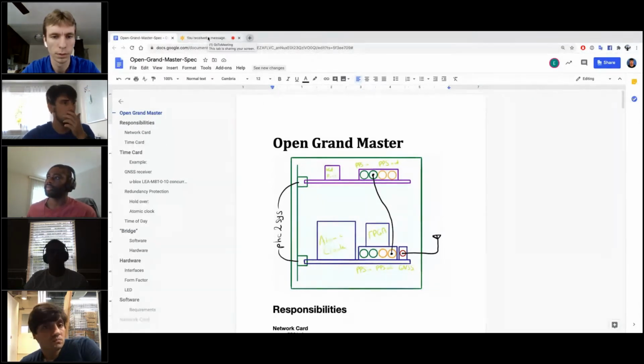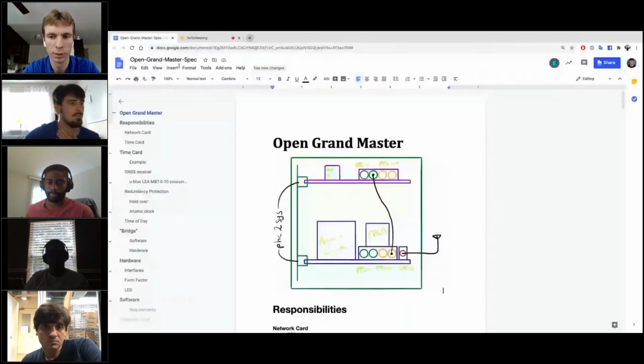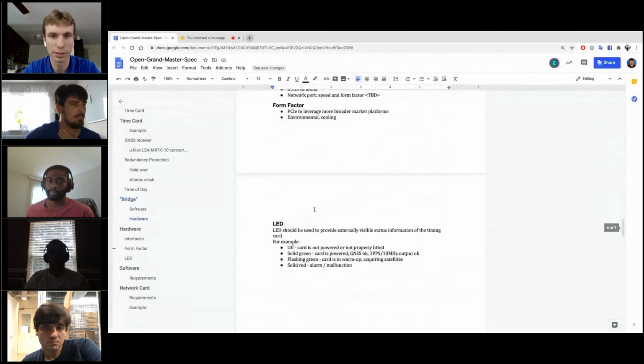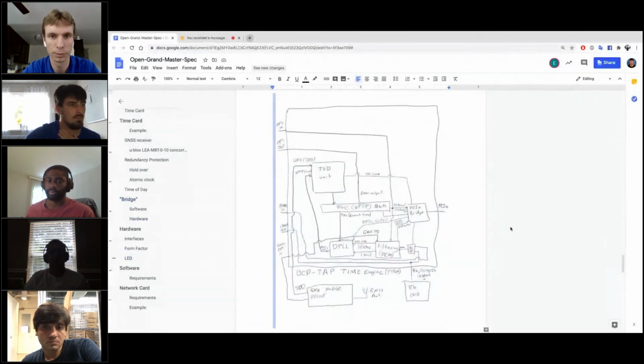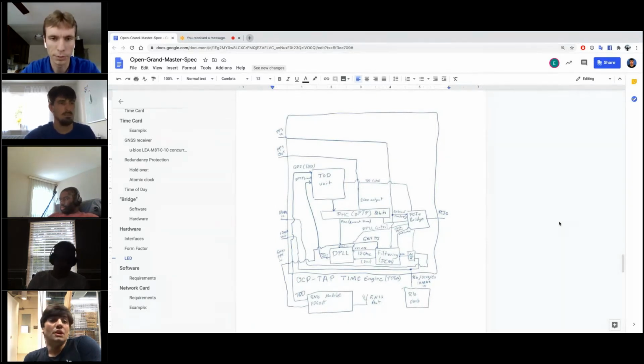Oh, good, sure. Yeah, you were showing the block diagram of the FPGA, and as I understand, your most basic approach is to just adjust the counts. So when you're comparing GPS signals with the rubidium atomic clock, in the most simple version you adjust the count in the digital counter, and then you're limited by the resolution of the counter of your internal FPGA clock. Let's say if you're running at 400 megahertz, you get 2.5 nanosecond resolution. And then you're suggesting not like that.